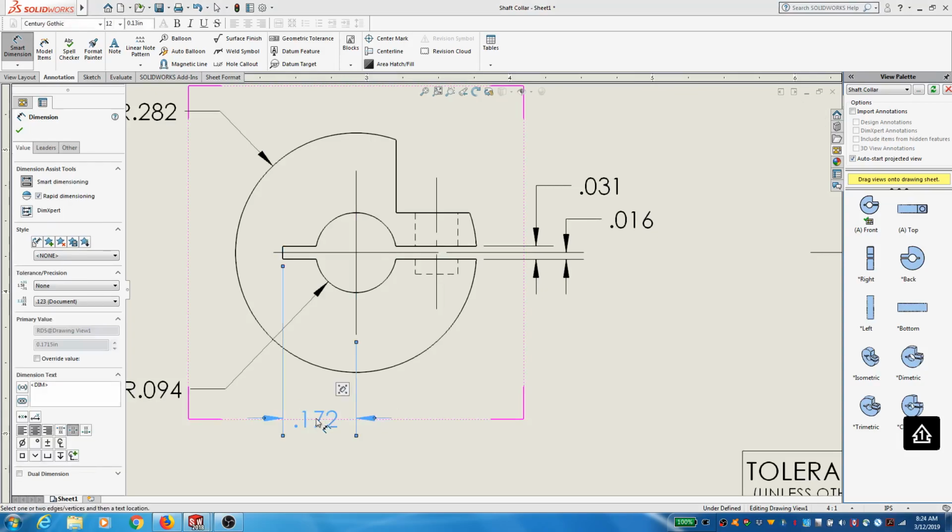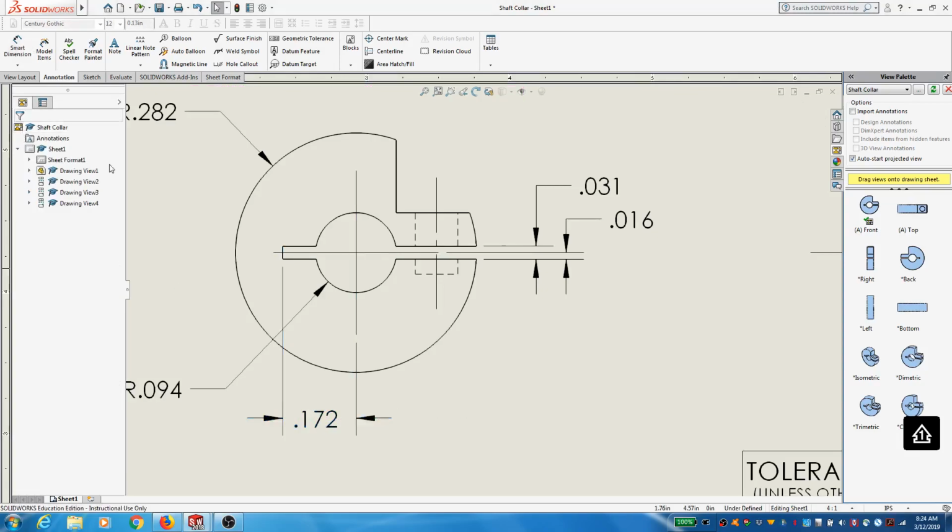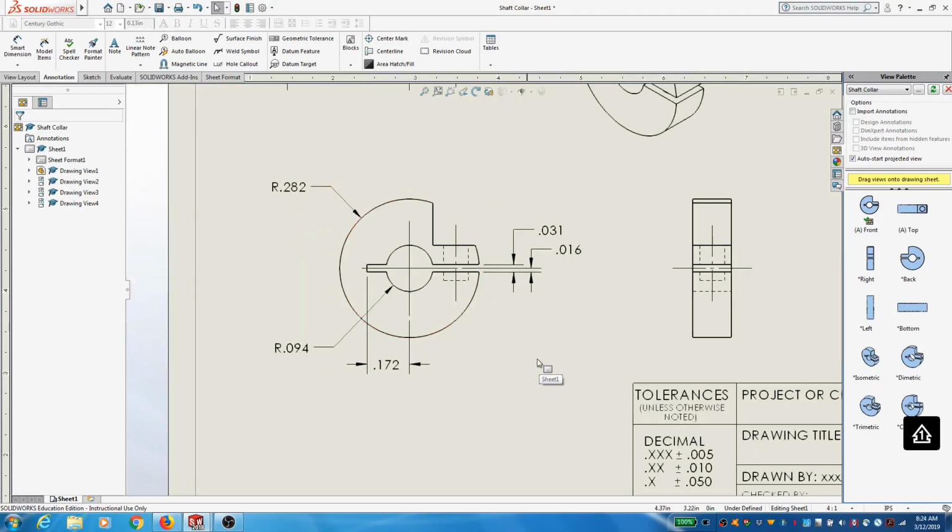Okay. So that should be the entirety of the slot. Let me just double check. I've got my circular hole, then I've got my slot, and I've specified the width. On this side it goes all the way through, and on this side it's coming back a certain distance, and I'm specifying it from the center line, or the center mark, of that circle. Other things, this hole is obviously concentric with the larger part, or with the outer diameter there, so I can leave that alone. Okay.